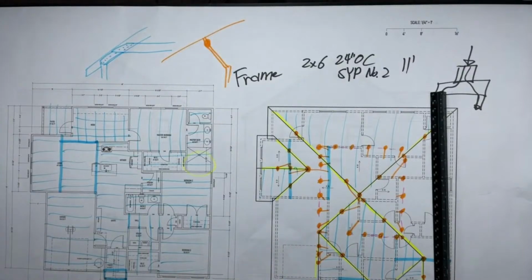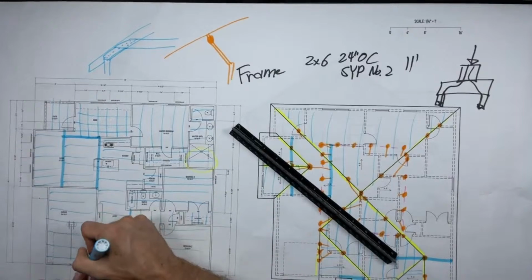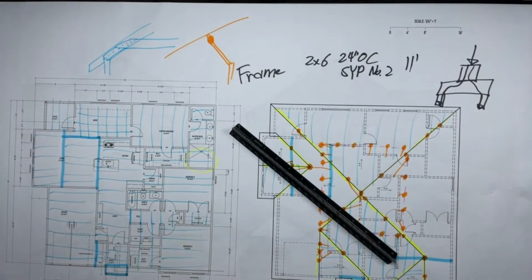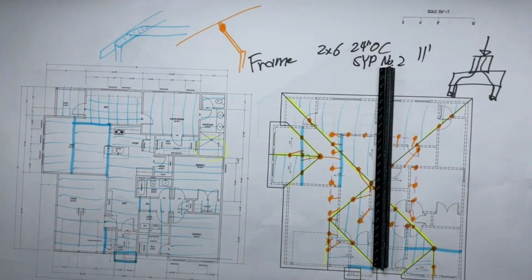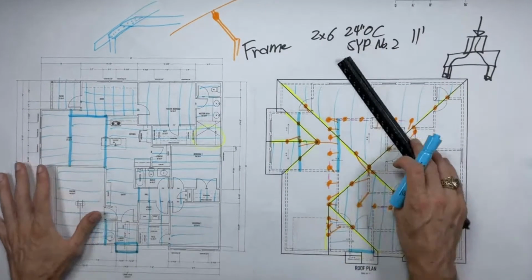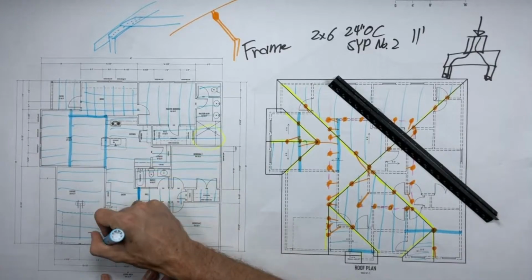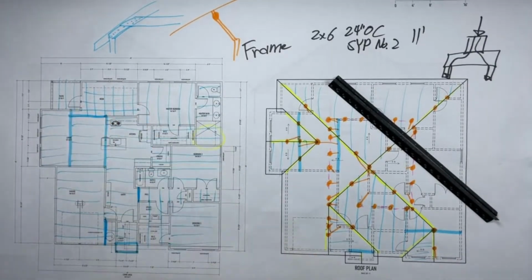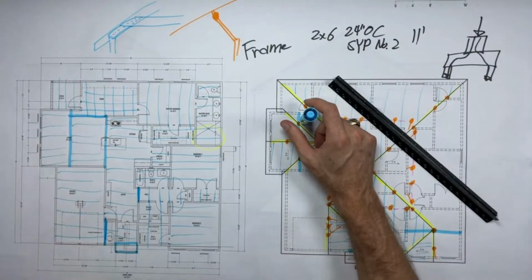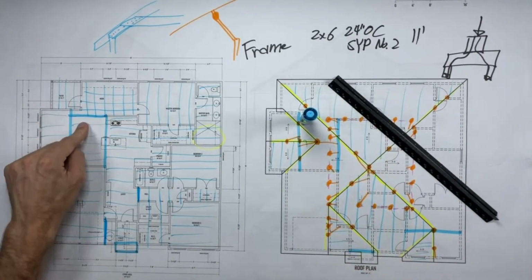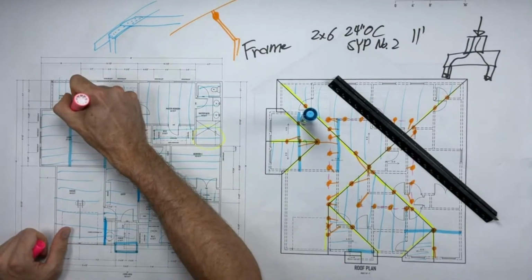All right. And let's look in here at these ceiling joists. They're going farther than 14 feet. So let's throw in a little 2x6 beam, something right there, just to break the span. And that's pretty good. Okay. So we've got a beam here, here, and then over here. And for the first time, I think, on Frame It Fridays, we are actually introducing a hanger. There's actually going to be a hanger, folks, between these beams right here.